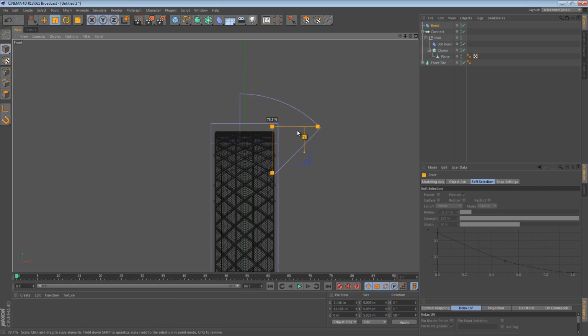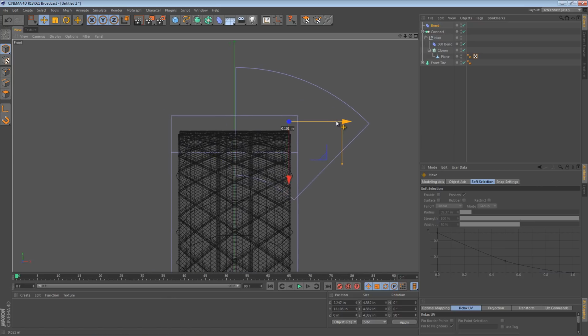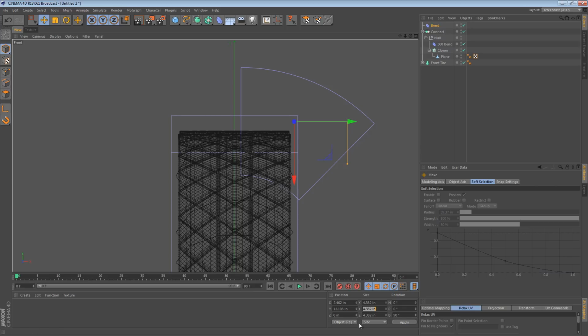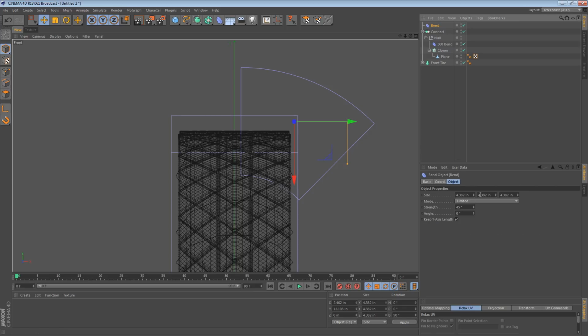And we can just scale it down, just looking at it, and you can see it's almost near the center there. Now, to make it perfectly at the center, I think we can use the same trick, where we take its dimension, and then we make that its x position divided by 2. So it's perfectly on the center right there.